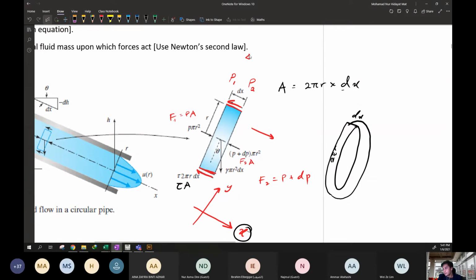So the delta P is basically pressure 2 minus pressure 1. So from here, in order to get the F2, P2 is equal to delta P plus P1. That is why you can see F2, or simply we call this P2, multiplied with the area. Now you understand, everyone, do you understand about these derivations? Why is this P plus dP? Because this is from this one.